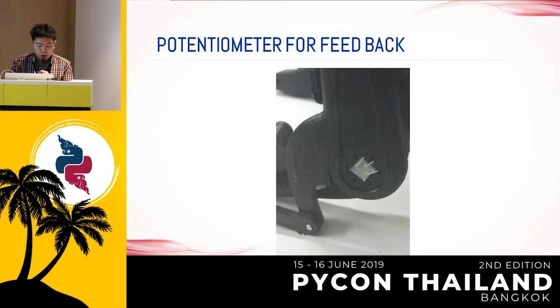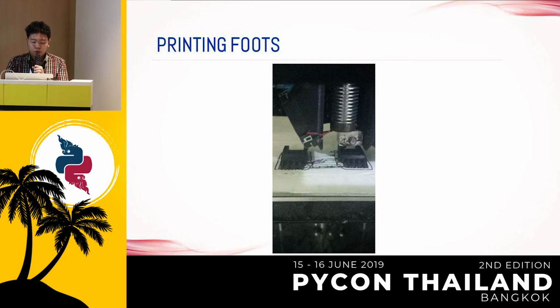Okay, so you need the battery. The battery that you are going to use is the 2-pack of the 7.4 volt 4000 milliamp. It's actually a pretty good one for using with the robot in a small pack size, because the robot needs dexterity and needs to move fast under the lowest weight, so it is not losing energy to the weight with the actuator.